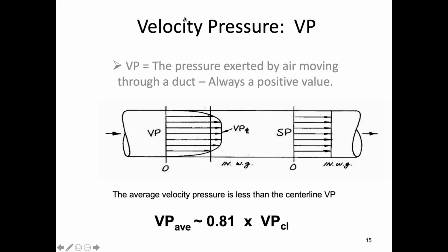When air is moving through ductwork like this very, very slowly, it's called laminar flow. Laminar flow might look kind of like that area that we have on the right side, where all the air is moving through the ductwork at the same speed. We don't really get that in ductwork. Air is moving through there relatively quickly, and there are eddies and turbulence and so on and so forth. So we get non-laminar flow. And what happens there is, as the air is moving through, the air that's close to the edges of the ductwork is affected by friction against the ductwork, so it's moving slower than the air in the middle of the ductwork.